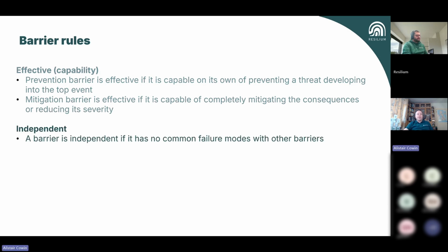The other side of it is independence, and common failure modes is a real thing. If you've done any fault tree modeling, you'll know that this comes out quite loud and clear. And I think it's really useful to have that mindset with this of, are we reliant on the same power source? Are we reliant on the same piece of data? And similar, the smoke detector is very similar in that regard, in that if the sensor doesn't transmit the signal, the horn doesn't go off.